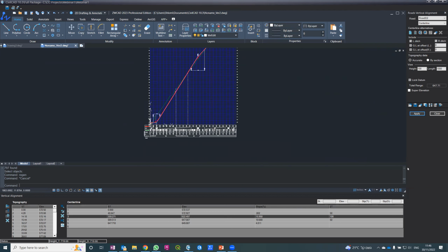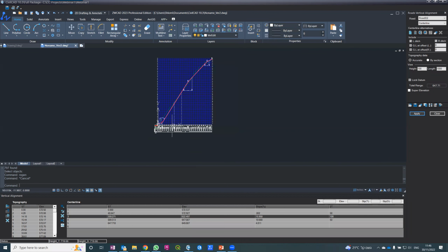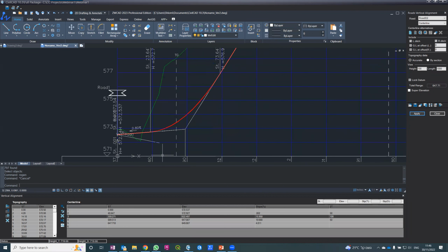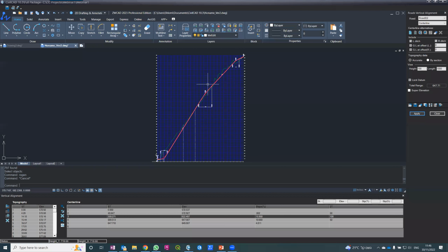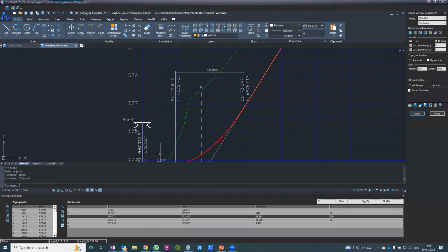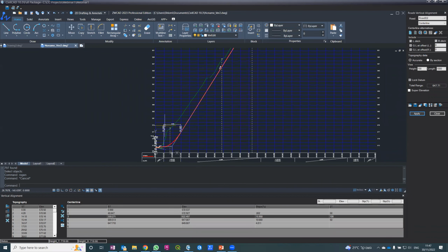No questions. Okay, fine. I have mass balancing, not automatic. Yeah, well, I assume you are talking about the mass flow diagram. We have a mechanism for it, and if you're talking about earthwork calculation, we have a mechanism for it, if I understood you correctly. So we have a mechanism to balance the earthwork. In this case, I'm not sure that it's a good one, because we have other restrictions. If I use it to balance, then the junction will fall out of place. But there is a mechanism for mass balancing of quantities, and it's also used to create a mass flow diagram.